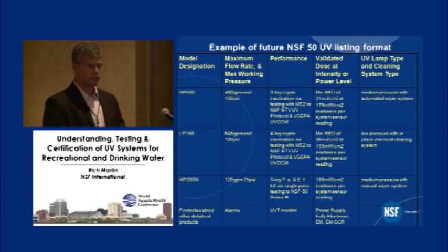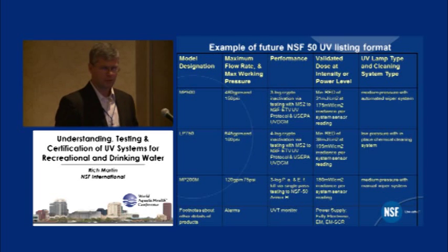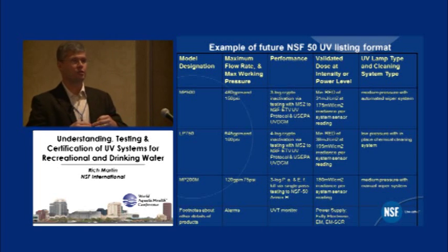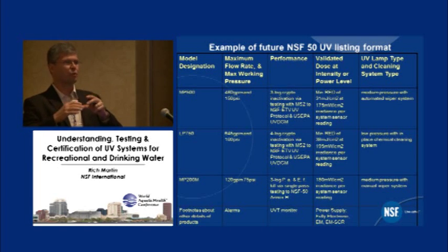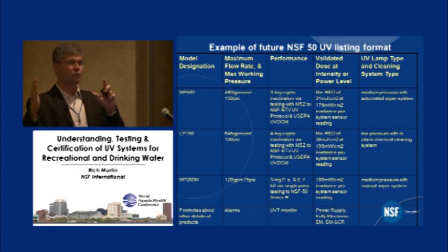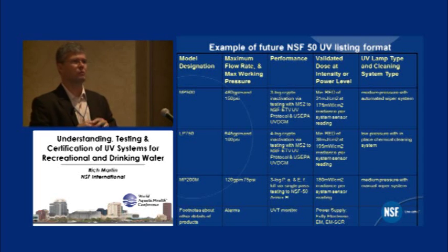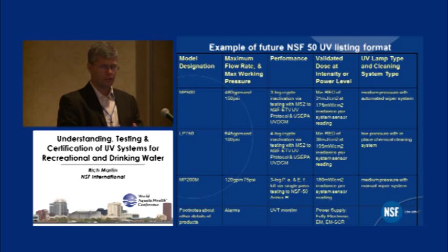So was that at a certain level of irradiance? That way you always have to operate your system at that level of power or irradiance, the power received at the sensor. So there's two different things. There's power generated, that's nice, but what power is actually received and detected, i.e., is the water very low in terms of its transmissivity, so it's really preventing transmission of that light. So that irradiance factor is so critically important.